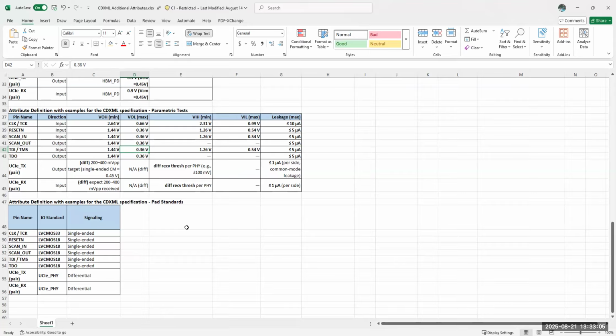DFT has baby steps for the parametric test, mainly to make sure that the sample preload and then the EXTEST kind of instructions work appropriately. And so in Intel, you're right, they deliver a very minimal pattern, and then the ATE guys expand it for all the voltages and levels based on that initial baby step pattern.